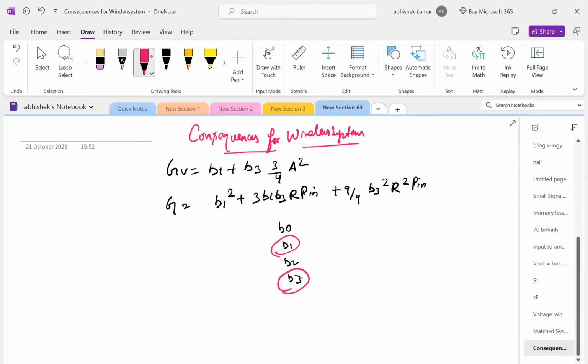Now, with a modulated signal, phase modulation and frequency modulation are okay, since the amplitude is constant. But amplitude modulation and QAM, quadrature amplitude modulation, have varying amplitude, so the amplifier gain varies and the modulation will be distorted. Are you getting me?